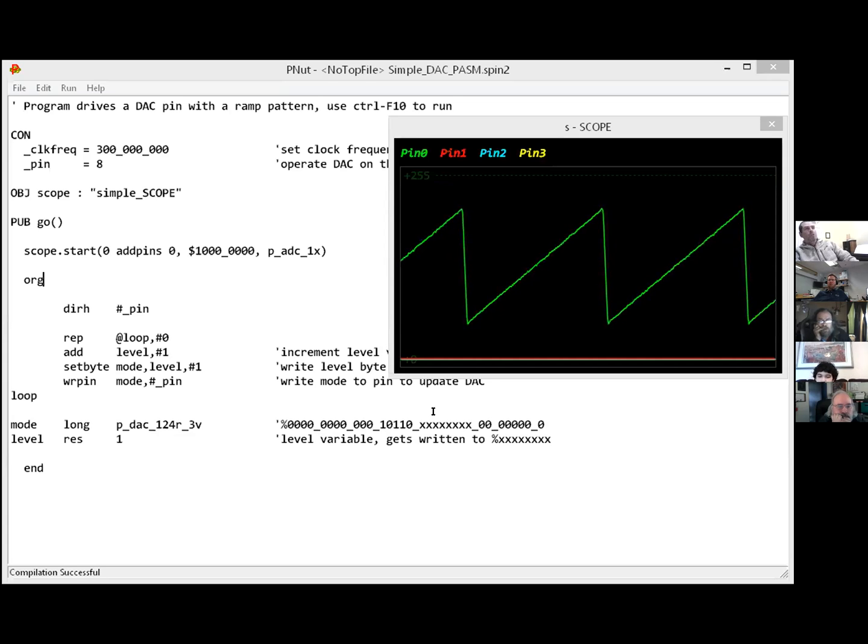Because this is like the low level pin configuration. It doesn't even have anything to do with smart pins. So that's why we don't use WX or WY for this, because we're just talking to the low level smart pin that is the pad, the custom pad on the chip. So it's not engaging anything else. It's just setting up the lowest level configuration for the pin. Does that make sense, Mike?